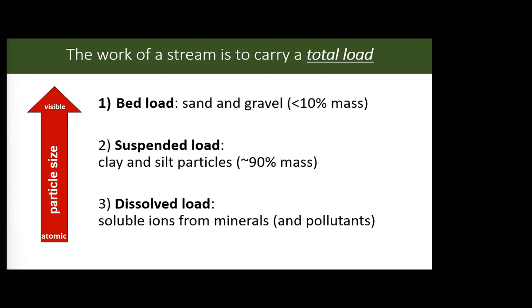Okay. So whenever we're talking about streams, a really important thing is the load that it can carry. That's basically determined by different types of sediment, so we're going to talk about the different sizes of sediment. We have 3 different types of load. We have the bed load, which is the sand, the gravel, real heavy, bigger stuff. You can see it with your naked eye. You can see the different grain sizes. It's about 10% of the mass, so not a lot, but significant enough that we want to calculate it.